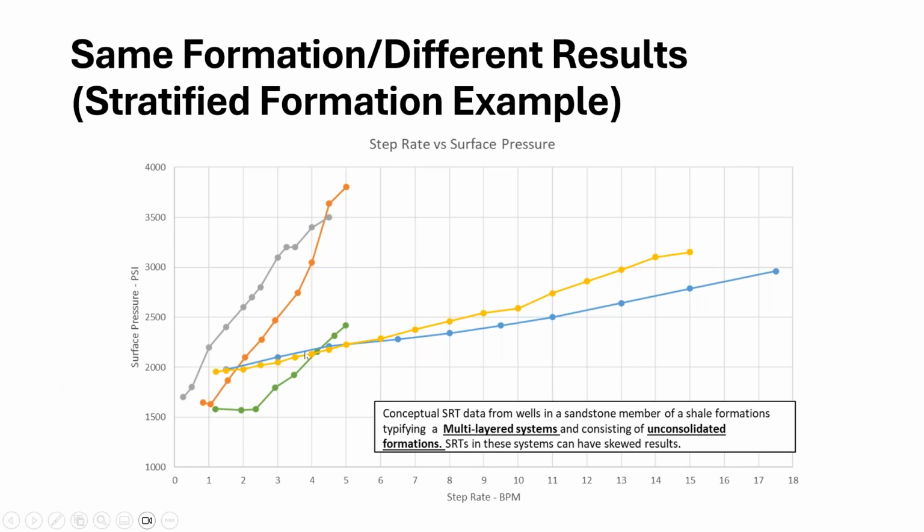Again, this is surface pressure data collected from step rate test permits. So we don't know exactly where the pressure transducer was put on the wellhead. We don't know the size of the pipeline laid to the wellhead. We don't know the general setup of the well. So there could be a lot of issues or conclusions that are not reached in this data.